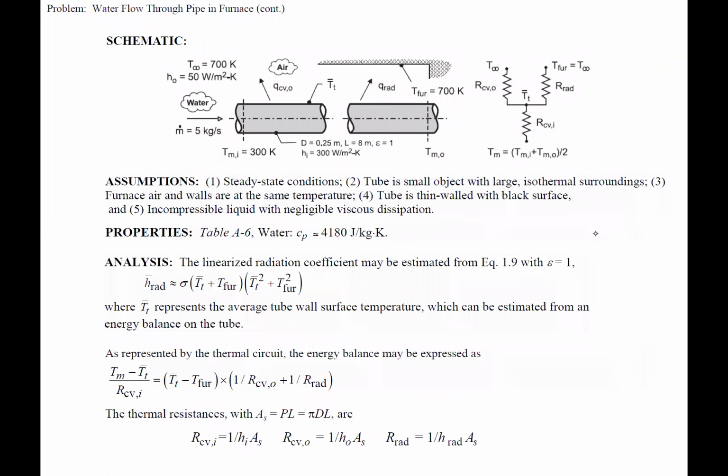Okay, so here is our mean temperature. This is inside the fluid, so that's from here to here. We're basically setting it up at this point right in the middle, at the average we're taking. All right, then we have our convection internally to that wall right here, and the wall surface is changing. So again, we have the tube average temperature.